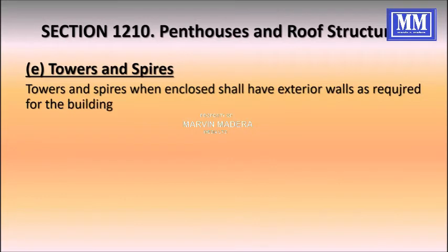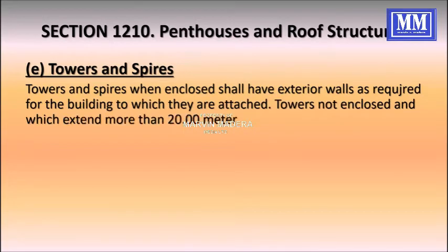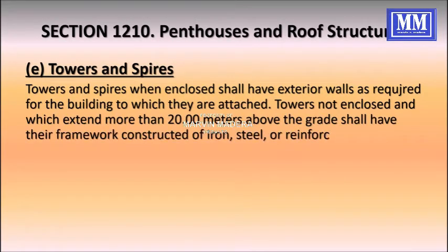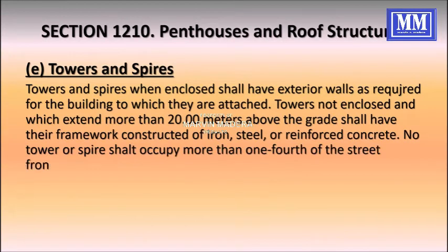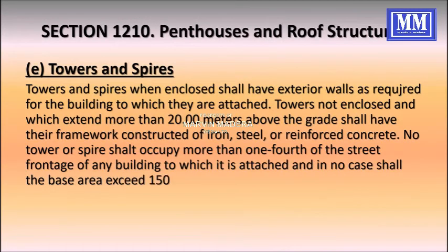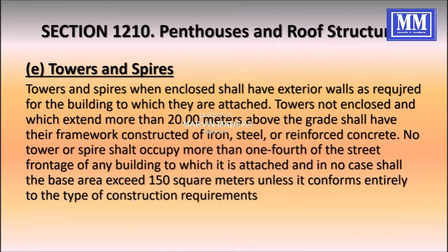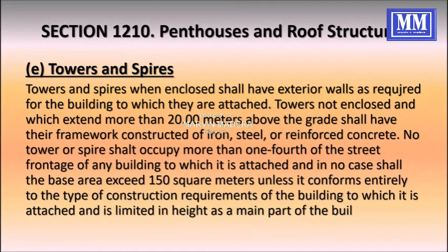Towers and spires. Towers and spires, when enclosed, shall have exterior walls which are required by the building to which they are attached. Towers not enclosed and which extend more than 20 meters above the grade shall have their framework constructed of iron, steel, or reinforced concrete.